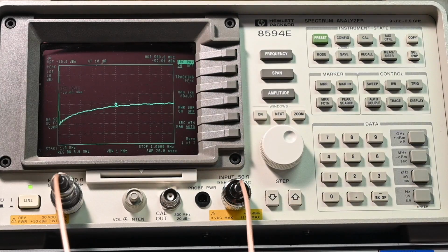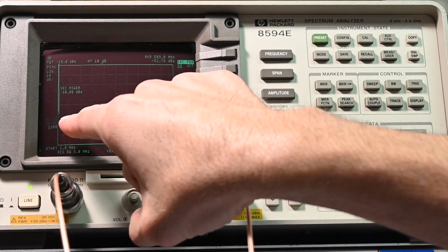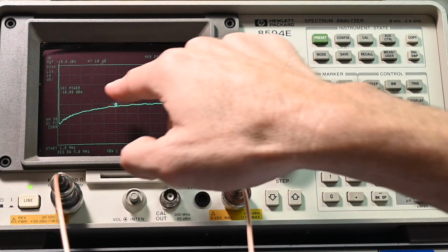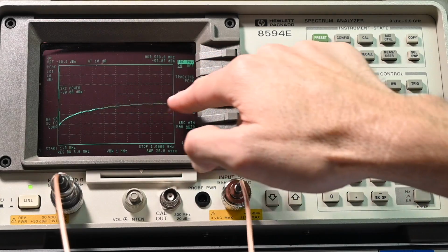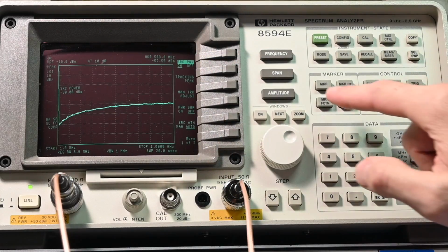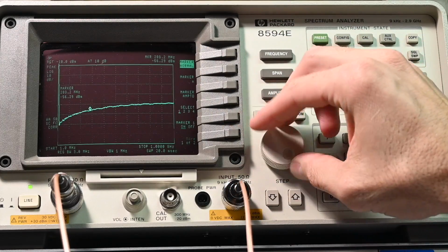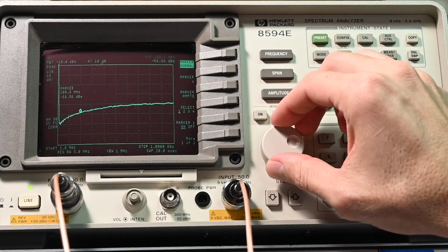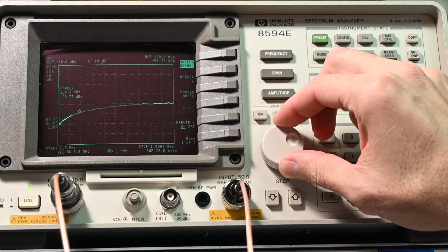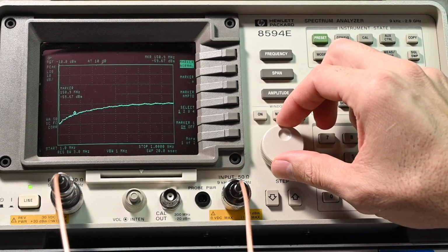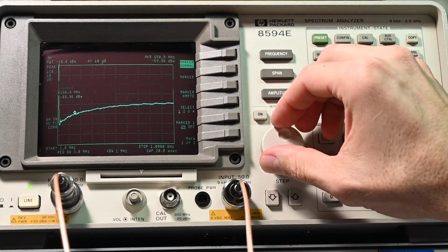And that doesn't look right. That definitely is indicating a bit of a problem. So look at how much attenuation there is on the low frequency, and then it comes up here and begins to flatten off. So we put the marker on here and let's get an actual reading. So the marker is this little diamond-shaped symbol. So if I go over here, right now that's 150 megahertz right there.